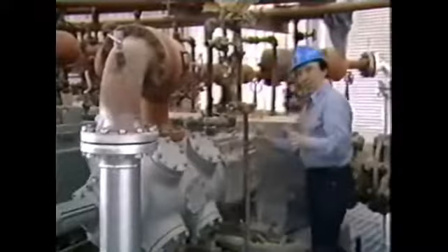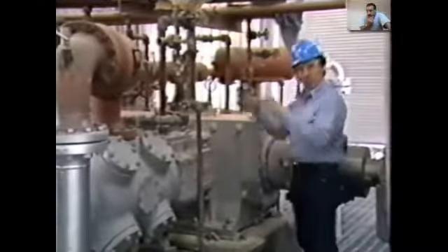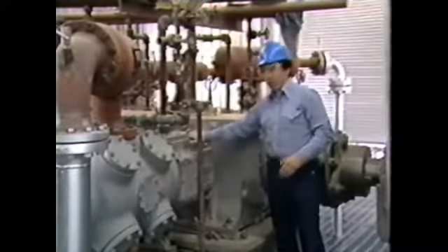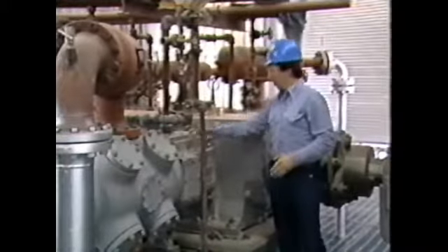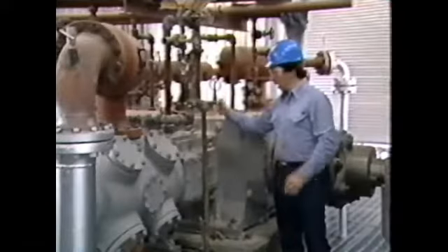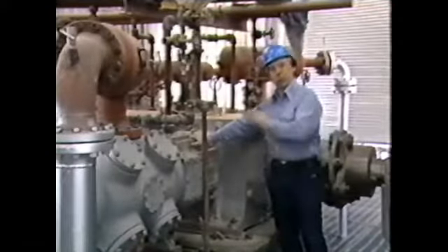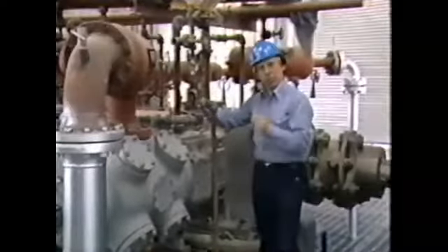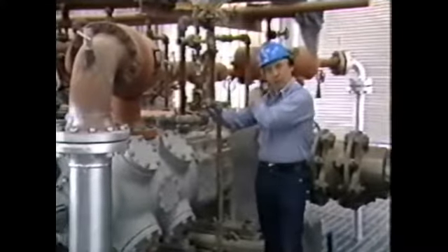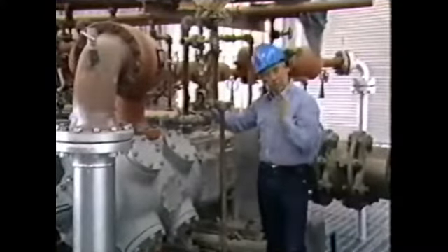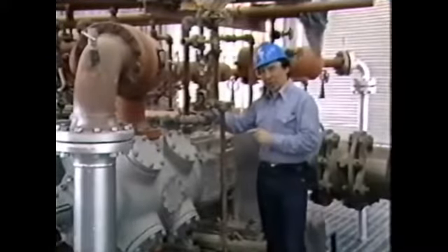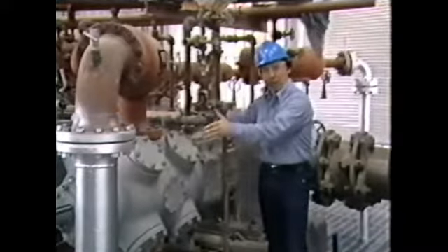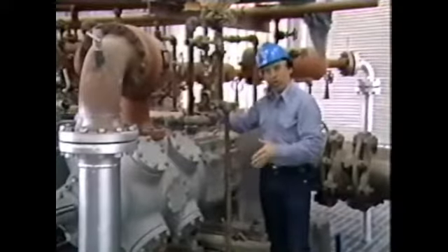Now, a typical reciprocating compressor consists of compression unit, drive unit, and the distance piece. The compression unit compresses the gas. The drive unit supplies the power, and the distance piece is the housing which joins the two units. Because the reciprocating compressor has numerous moving parts, lubrication of the compression unit and the drive unit is crucial to smooth compressor operation. In addition, the temperature increases within the compressor caused by the friction of the moving parts and from compressed gas. In order to remove this heat, cooling systems are also required.